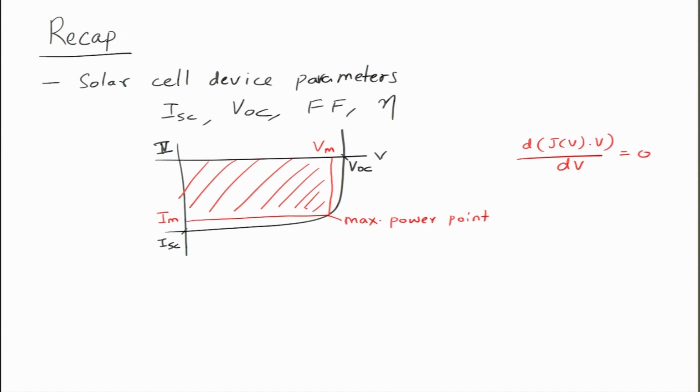So, this is the maximum power that you can draw out of a solar cell, which is within the experimental IV curve. The idea of materials and device engineering is that your aim is to make this curve as square or as rectangular as possible, which means that series and shunt resistance must be optimized. If you have a bad solar cell, it would appear like this. So, if you now want to draw the MPP in this, the MPP would correspond to something like this.